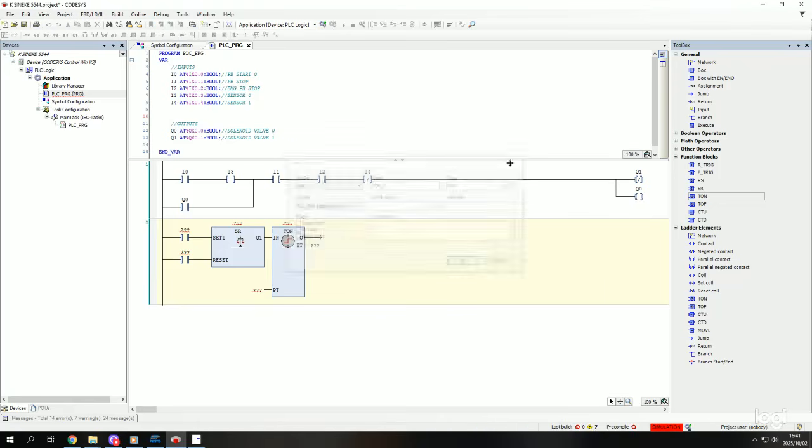Okay, lastly, you click here to insert; we always need an output. So you will always have your coil at the end, because these are your inputs and this is your output. So you're always going to have your coil there. So what is my input? What do we use to set or to start the process?